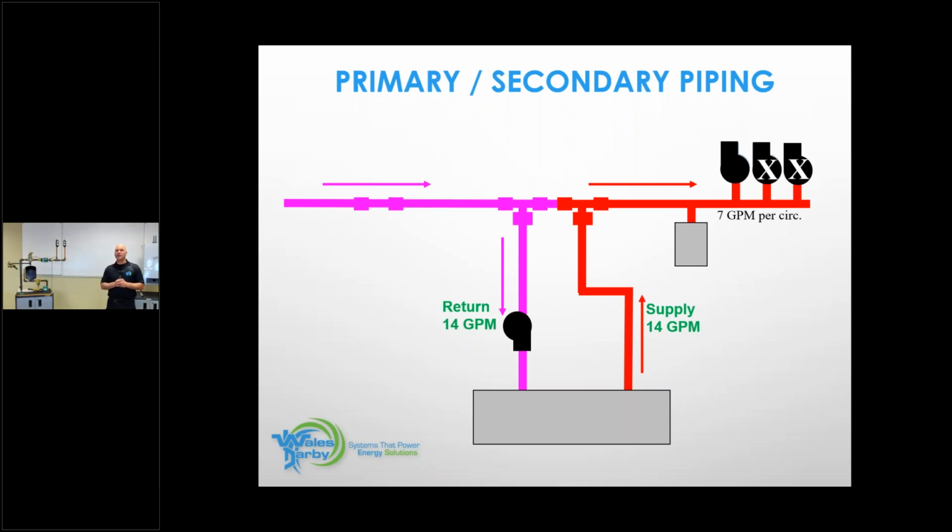We got 7 GPM in our header system. And here, I'll clarify a few numbers for everybody. There's our flow rate in our system, which theoretically is our secondary, primary system. Anytime you have water that flows through a T like this, that's called your primary circuit. Anytime you have water that comes out of the bowl of the T, this is the secondary circuit.